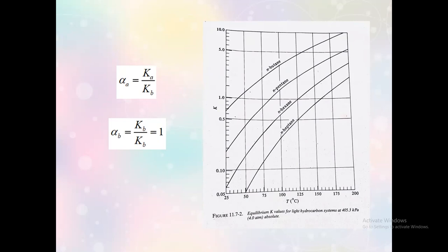It has to be based on equilibrium. So if you have this diagram already located in your handbook, so much the better. That way it will not be a problem of having to determine the mole fractions of, let's say, A and B, both in the vapor and in the liquid phases, for you to be able to find the KA and the KB in here. Okay, you just simply read it out from the diagram.